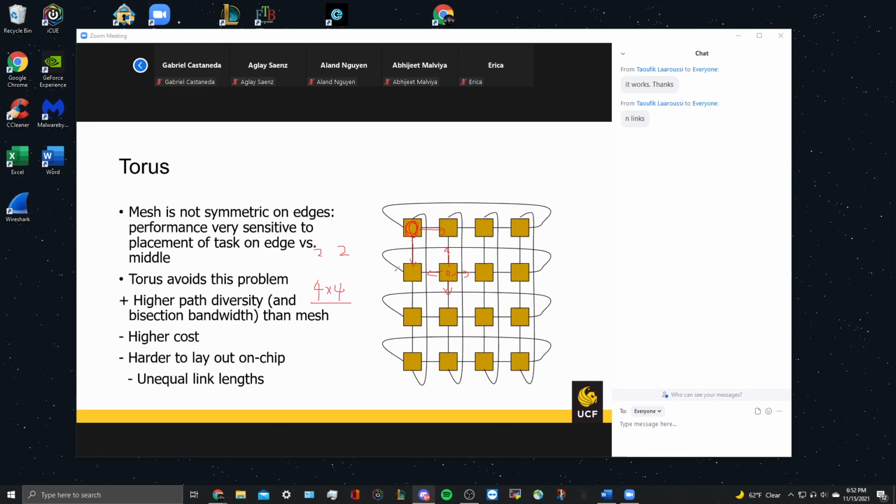But for Intel's design, they have 2 rings. So for a ring, what is the switch? It's just one input port and one output port. If it's bidirectional, it's just two inputs, two outputs. And for the other direction, we also have 2x2. But why is Intel's better than 4x4? 4x4 is 16, and 2x2 is 4 plus 4, so you have 8.